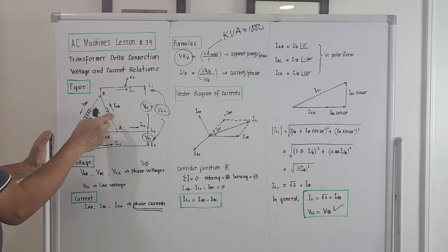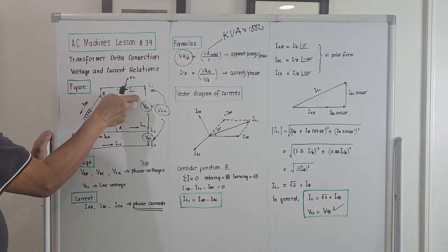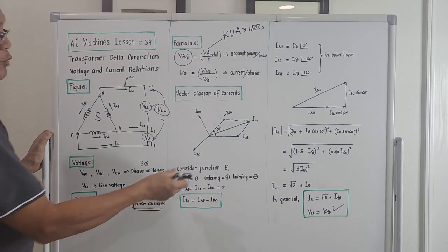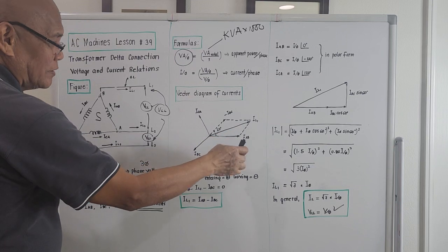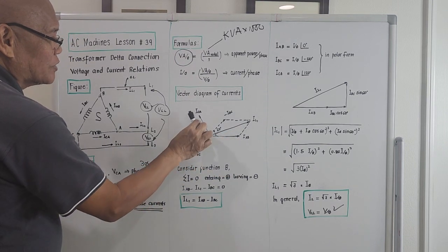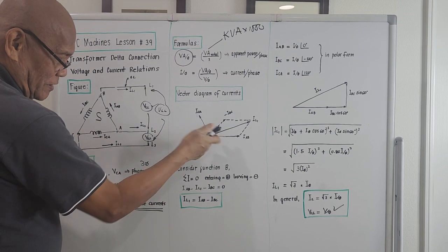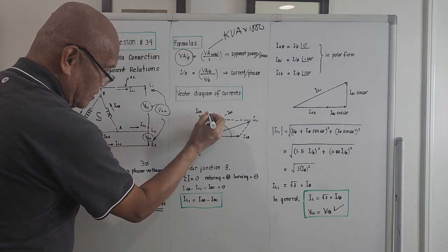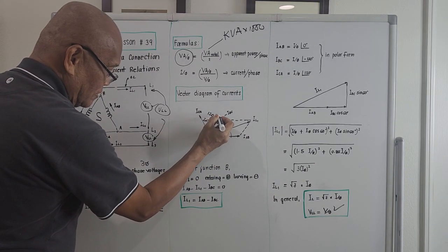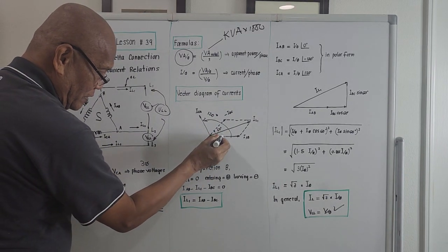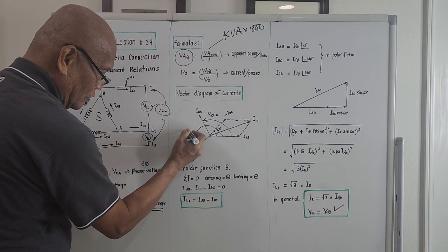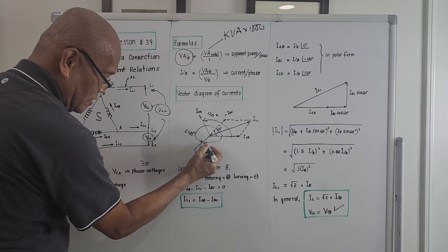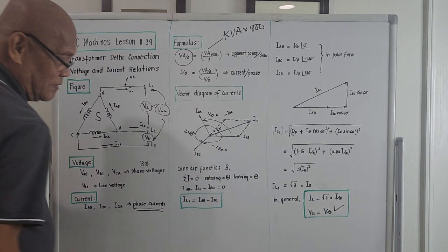So to derive the relationship of the phase current with respect to the line current, we need the vector diagram. This will be IAB, located at angle 0 degrees. I sub CA is actually located at 120 degrees. This is 120 degrees. And the third one will be 240 degrees. Or if you try to measure it clockwise, it should be negative 120 degrees. Right?